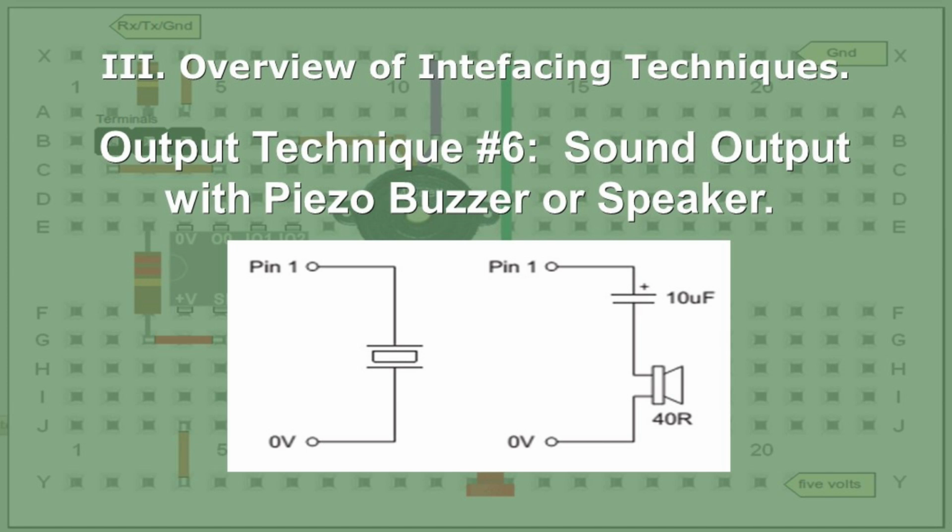Now you can use a 40 ohm resistor with the PICAXE controller. Notice they use a 40 ohm speaker with a 10 microfarad cap, and you can hook it up that way. But that's with the PICAXE controller. But a piezo buzzer is such a low load that you can interface it directly in many applications.